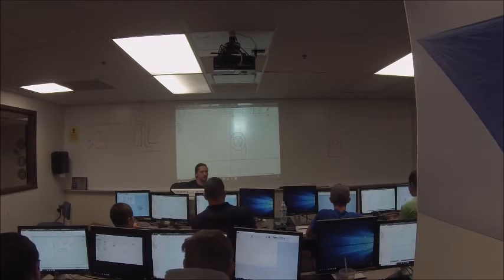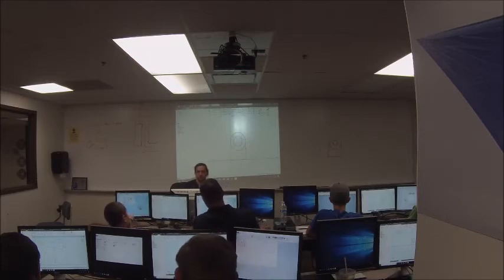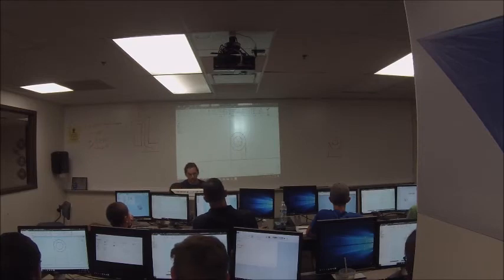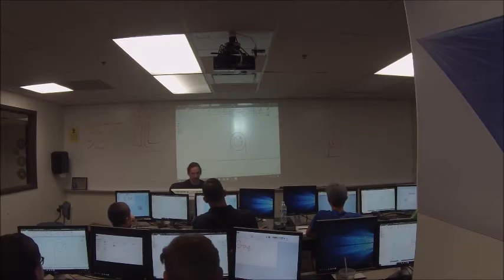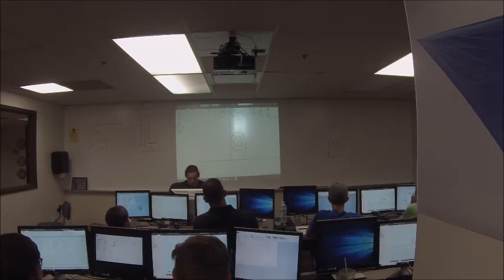Click on the line and hit the little circle on the end of it, and then drag it and attach it to the circle. Mine says it already exists. Oh, snaps is what I'm thinking. Right, yeah. So I can click and drag on the endpoint of the line and just snap it to the circle, like so. Click and drag and snap. Right, now I got a coincident constraint, now it doesn't move, right? That's easy. Why is it not? Undo it. There we go.